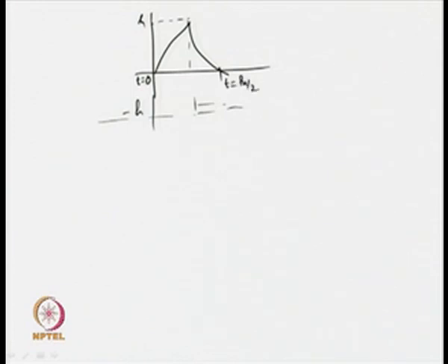So, looking at this positive half output signal of the system under relay test, we can set some conditions like y(0) is equal to 0, but y(0) is nothing but x(0), since the state variable x has been introduced and we have assumed that x(t) is equal to y(t). So, for this first order plus dead time system, definitely this is true that x(0) is equal to y(0) and that is also equal to 0.